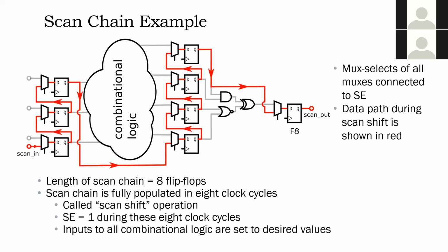The flip-flops are connected sequentially in the scan chain. And this is what ends up happening when we introduce these muxes and create scan chains. We have sort of burdened the logic a little bit. We have added these muxes whose only purpose is to enable testing. They have no functional purpose.